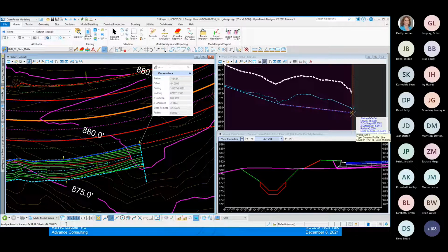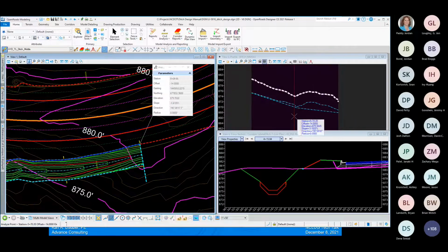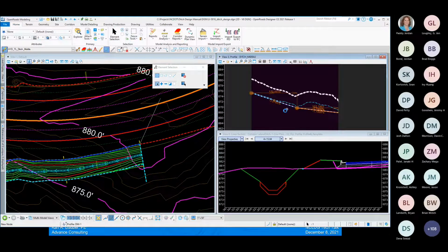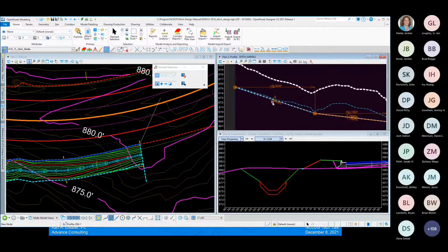I'm going to write those down. I already know what the elevations are. The other pieces of data I need are the slopes. I'm going to record this, which is 3.2765%, and this is 1.15%. Now I have all the information I need, and I can start the process of creating the point controls.